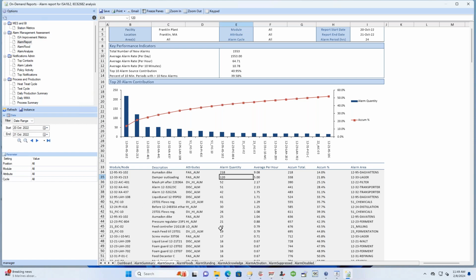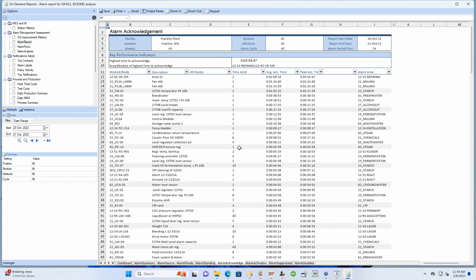And we also have a lot of general housekeeping information, I guess, if you will, in this report. For example, we look at the concept of alarm acknowledgement time, the average time it takes to acknowledge alarms. We have alarms that are taking hours for people to even acknowledge them happening. So we're looking at not only the condition of the alarm itself, but what's happening with the operations, with the operators. Why is it this condition specifically they're taking so long to acknowledge? This is something we would investigate more as a process and procedural kind of thing.